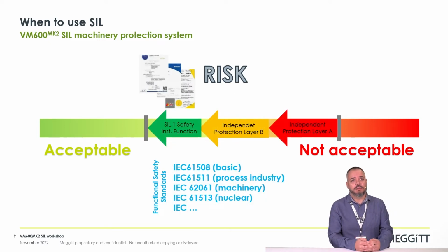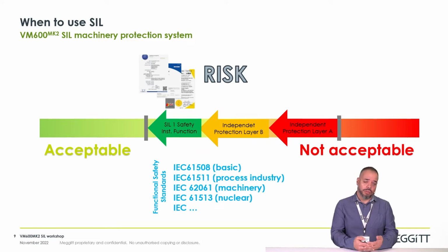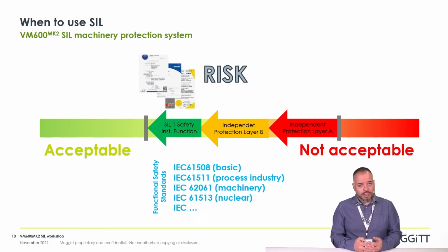And this is basically the same for a protection system. You can also use your own judgment and also a set of standards. These functional safety standards will guide you in the evaluation of the risk and also in the quantification of the risk reduction factors that you need to apply, again to bring it down to acceptable levels. More specifically, the functional safety standard IEC 61508 is a generic safety standard that allows for the development of a uniform technical approach that can be applied to all safety systems in electronics and related software. Then we have other standards more specific to each type of industry.